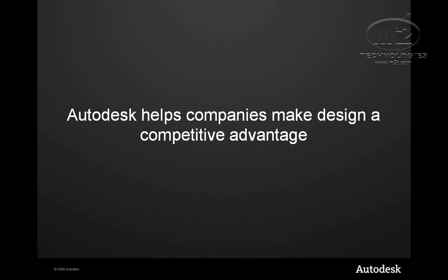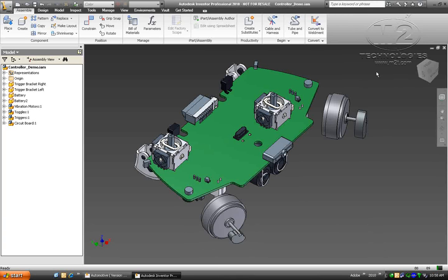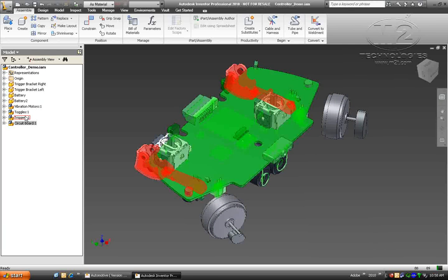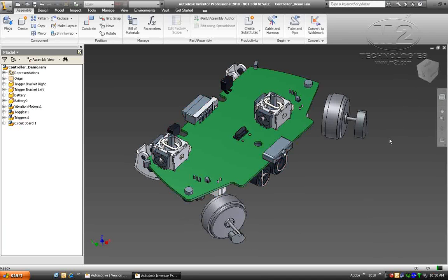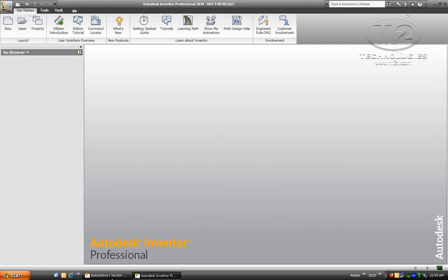First thing we're going to take a look at is the transition from Inventor to Alias. So here we have an Inventor assembly, and if you take a look at the browser over here, we have some subassemblies and then some parts on those subassemblies. So this is what it looks like inside of Inventor before we open up the assembly file inside of Alias. So this is typically what engineering would kick out, maybe some product internals. It could also be some 3D ergonomic data. So we'll take a look at what that looks like inside of Alias.